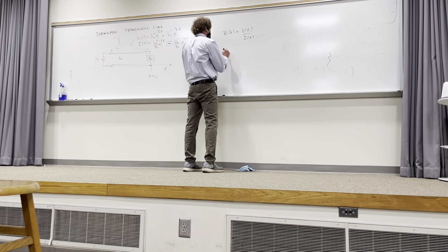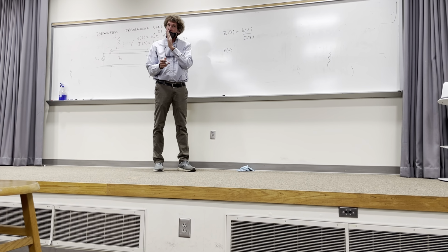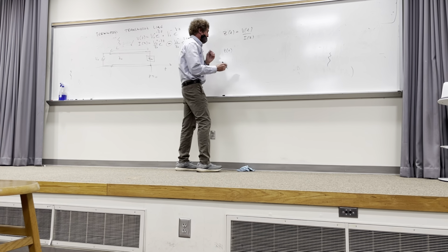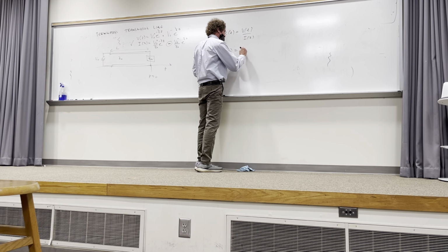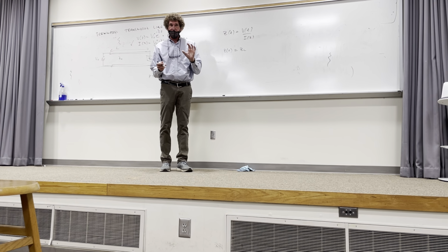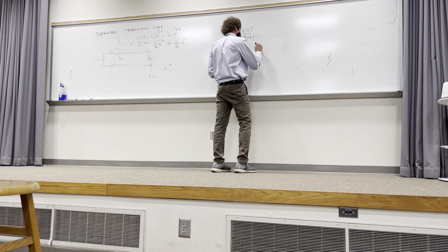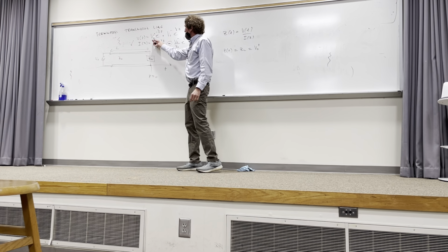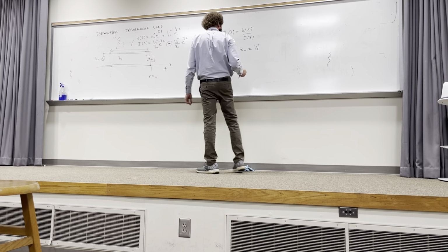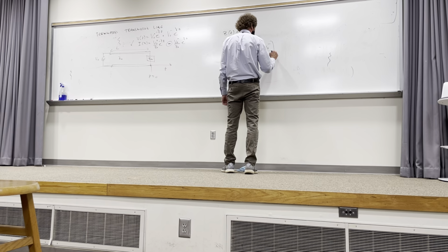Now, if you're at the load, if you're at Z is 0, so remember, I stuck the load at 0, right? If you're right there, well, I know what that impedance is. That's ZL, isn't it? The ratio of voltage to current at the load is the load impedance, isn't it, class? By definition. It's also equal to V0 plus, take this equation, let Z be 0. So it's V0 plus plus V0 minus over V0 plus minus V0 minus, and it's this times Z naught.